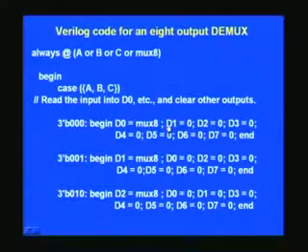And you notice that D1 through D7 are all made zeros here, because when it enters, it can enter from any other state. So unless you make them zeros here, it may hamper the performance. It may have come from a latch, and it may latch onto the old signals, right? And it is better to give this here.